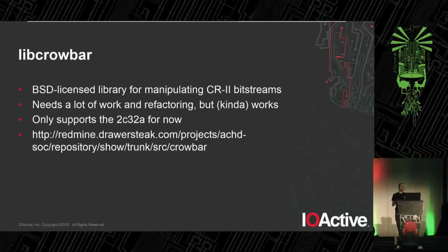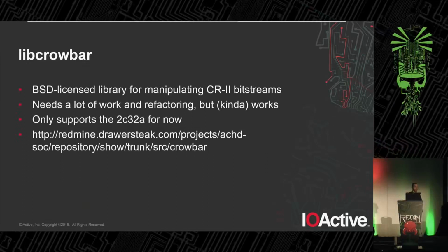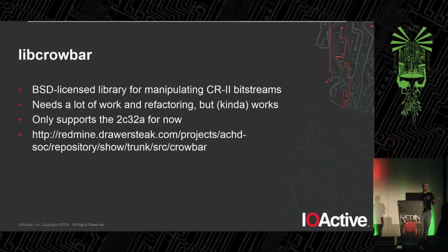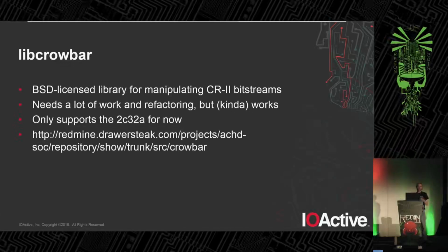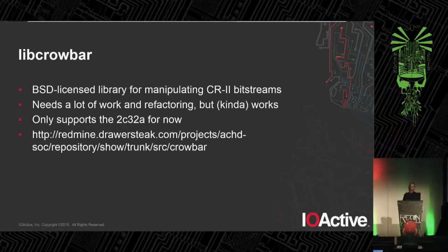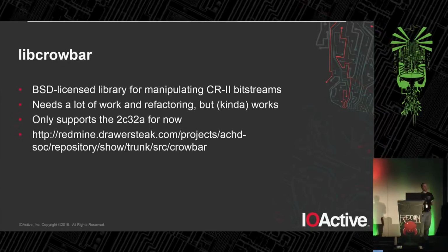I've decapped it. I've looked at the top layer. It's just a 2x2 grid of function blocks instead of 1x2. The ROM for the routing fabric will have to be decoded separately, but that shouldn't take too long. The ordering of the bits will have to be decoded, but again, that shouldn't take too long. I can probably just brute force it. And the macrocell configuration and everything else is pretty much exactly the same.